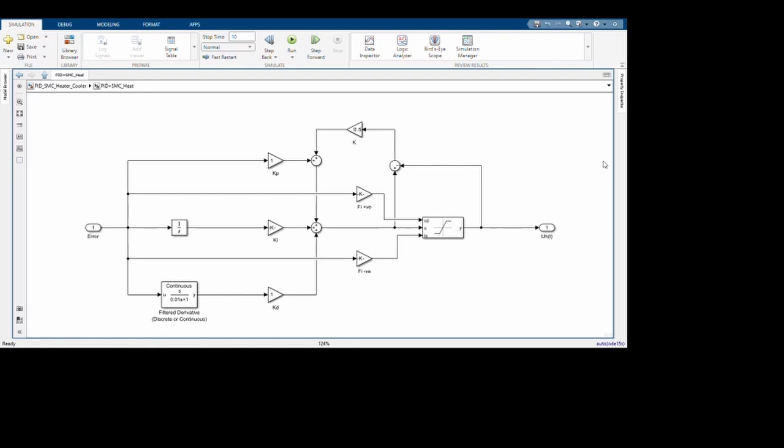In this case, we use another type of control strategy called sliding mode control, which is basically defining a sliding surface on which the system is going to act. That type of controller is a very good robust controller, but there comes a downside with it. It does something known as chattering, which is very high frequency switching, which can damage a lot of our MOSFET switches or relays. So here we have gotten the best of both worlds. We've gotten the simplicity of our PID controller and the robustness of our sliding mode controller.